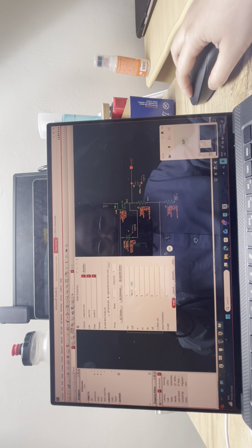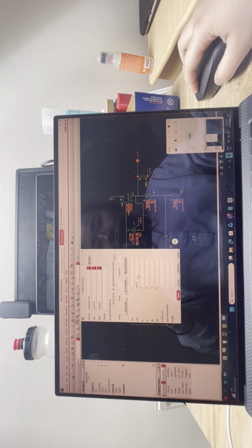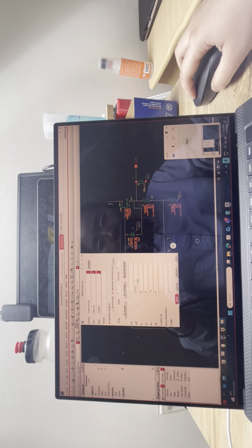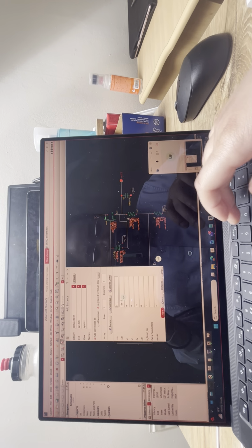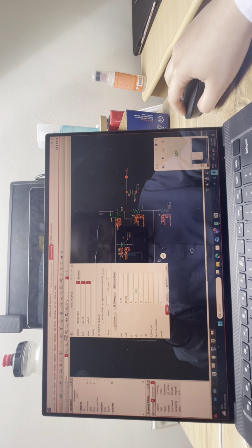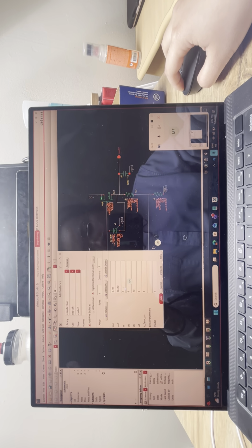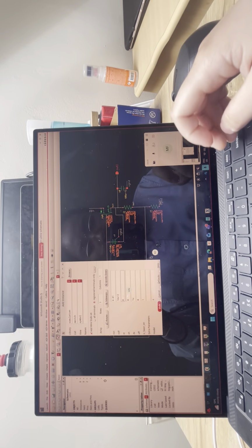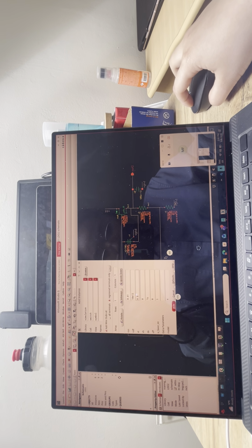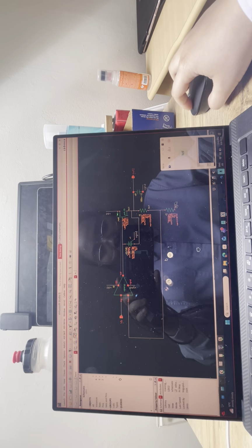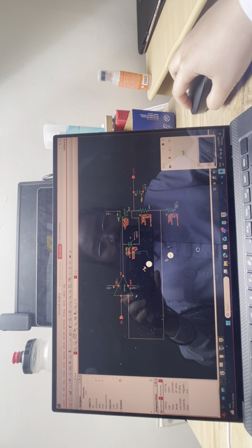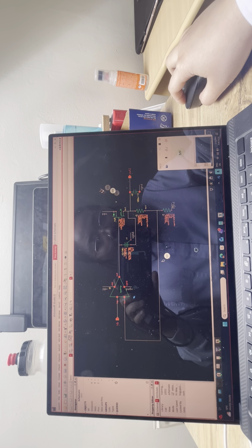Change the R on there to maybe 0.1 of an ohm or 0.01 of an ohm. And then you see the VT there, change that to, you could say, 0.5 volt. That's all we need to do with it. So if you can hit enter on that, then that should give you a switch that you can place somewhere.